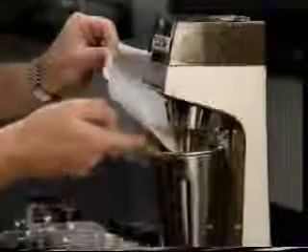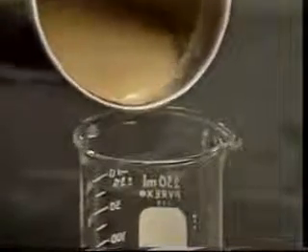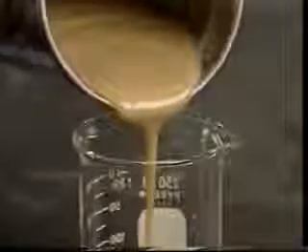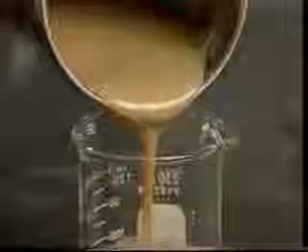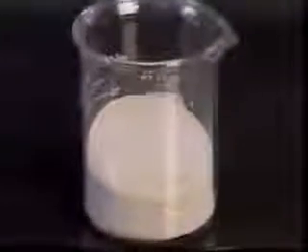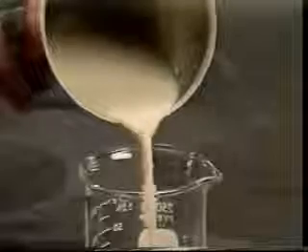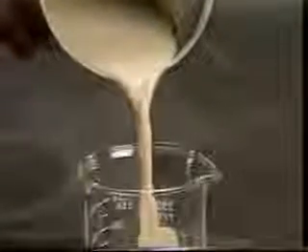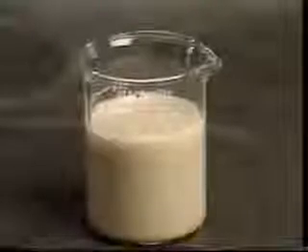Clay minerals are crystalline in nature, having thin crystal platelets that stack together face to face. When mixed with water, these platelets separate as the clay hydrates or swells, increasing the viscosity of the mixture. Another clay mineral, attapulgite, is commonly used in saltwater-based drilling fluids. Attapulgite does not swell like bentonite, but must be dispersed by agitation. Section 5 in your manual has additional information on clay chemistry as it relates to drilling fluids.